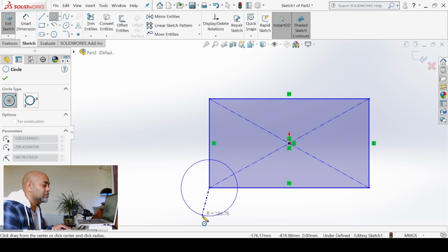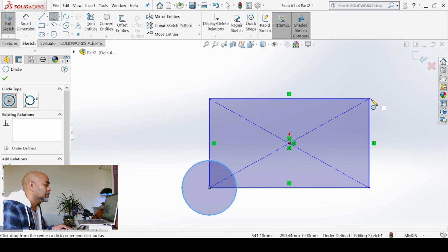Okay, that's fairly straightforward. I wanted that circle drawn. Point, right? Okay, maybe another circle here. But before we go ahead and do that, look at what's going on here. Horizontal, so that line is forced to be horizontal. This is a vertical line, so I know that. And that little green indicator is literally next to the element, so it shows that those are the properties of